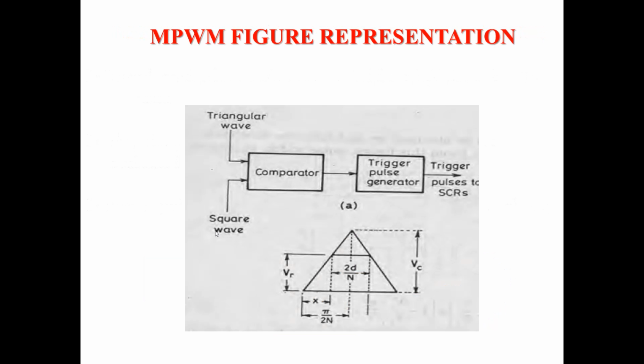From the figure given, it can be generated by comparing a square wave reference voltage VR of frequency omega with a triangular carrier wave Vc of frequency omega c.